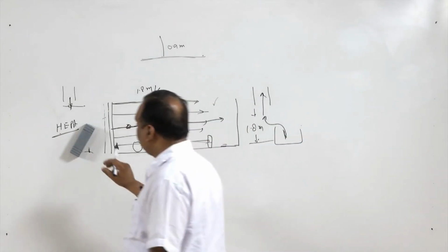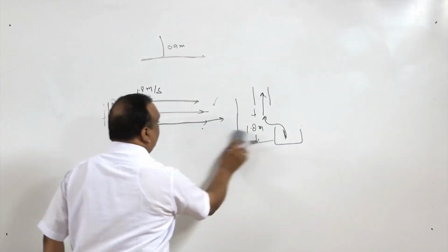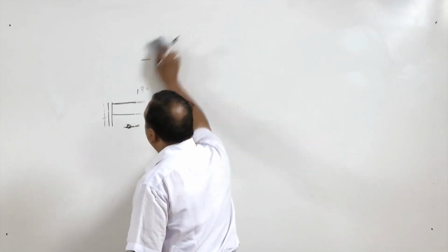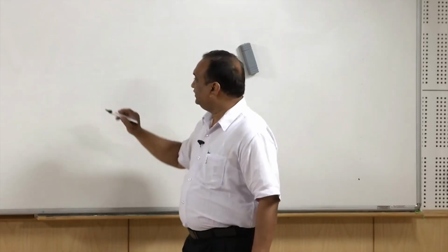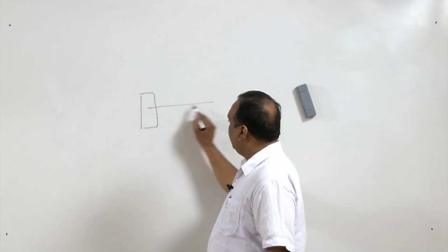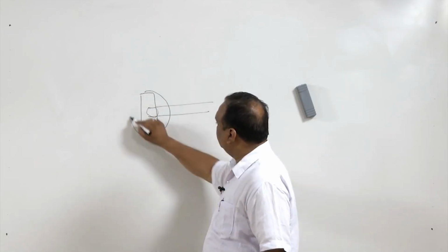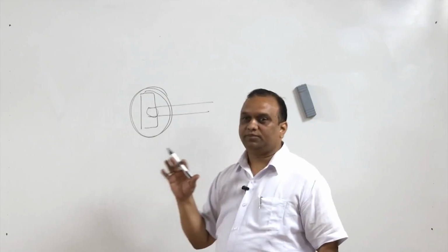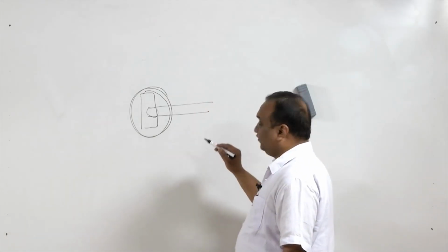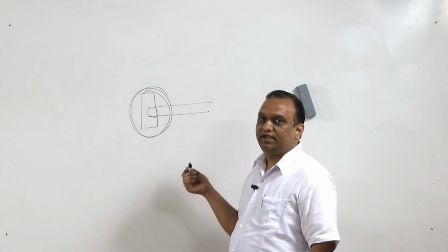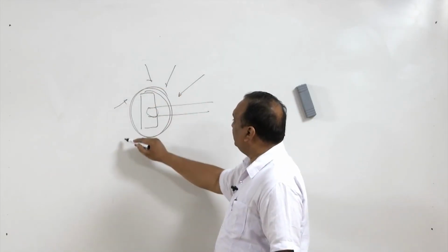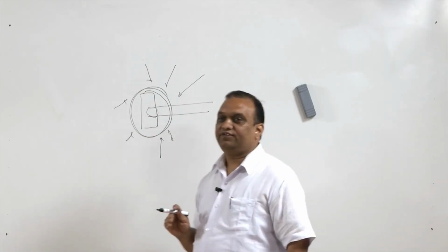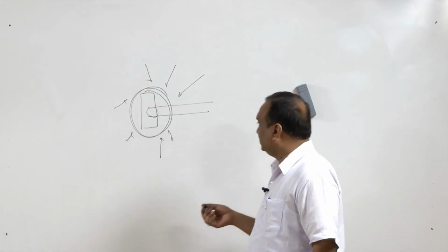In addition to this, in hospitals, personal ventilation is also provided. In general wards or in ICUs, suppose the patient is lying on the bed, the fresh air will come from the pillow and it will envelop the face of the patient. So, this envelope is created on the face of the patient with the fresh air, which is definitely at a slightly higher pressure, so that outside air is not inhaled by the patient. This is known as personal ventilation, and it is becoming very popular in hospitals, even in offices.